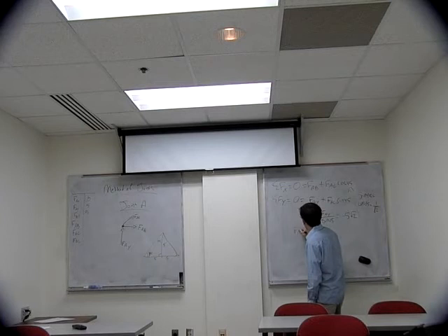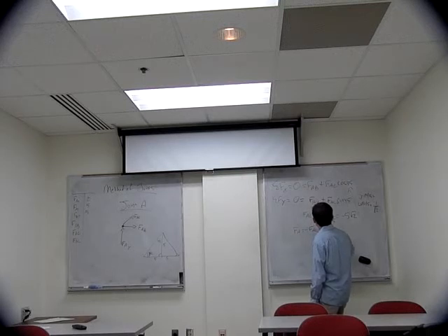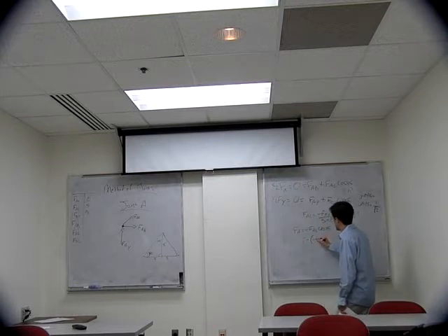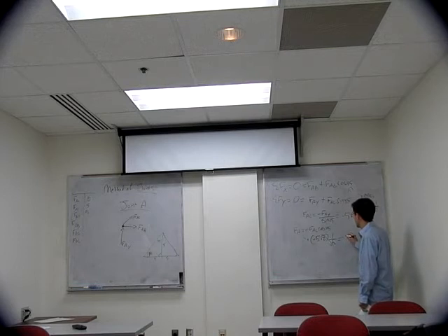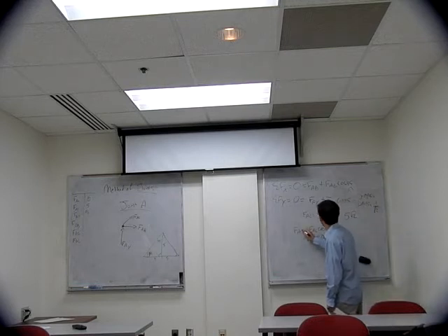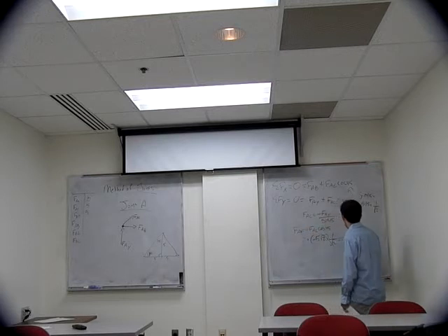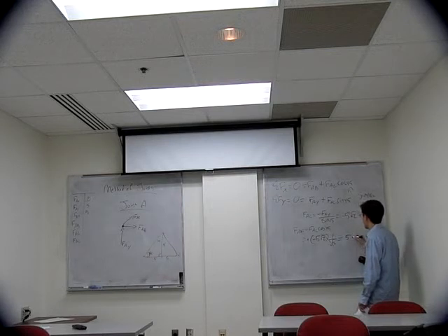So we have FAB is going to be equal to negative FAC times the cosine of 45. Plug this in, make sure you carry the negatives, square root of 2 times 1 over the square root of 2. Square roots of 2 cancel, the negatives cancel, so we find that FAB is going to be equal to 5. Remember, the units is kilonewtons.